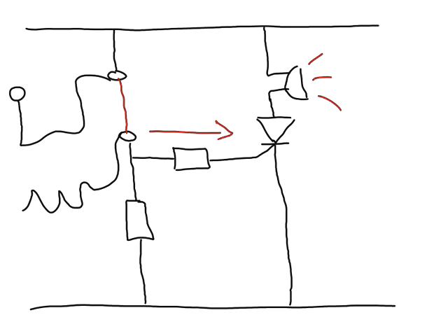But we also need a reset switch. So the best way to reset a thyristor is simply to short circuit its two terminals. So all we have to do therefore is draw in a push to make switch in that direction. Okay, so now even if the current, well, after the current pulse has disappeared and we push the switch, the thyristor will turn off. So there's bits of the circuit we need to label here.